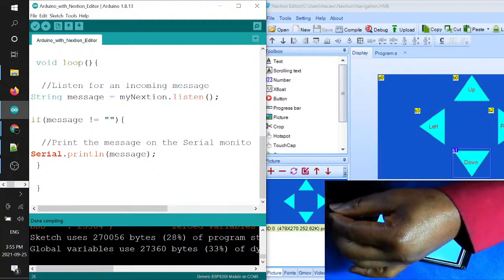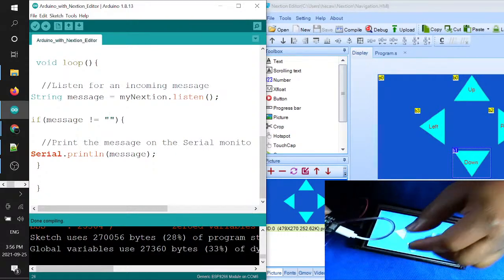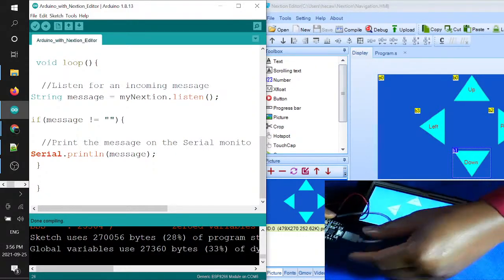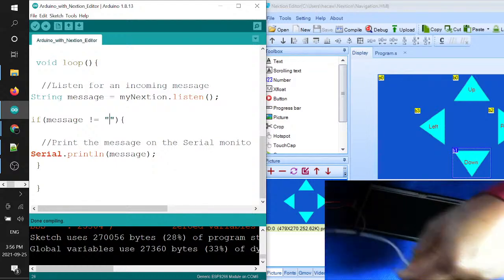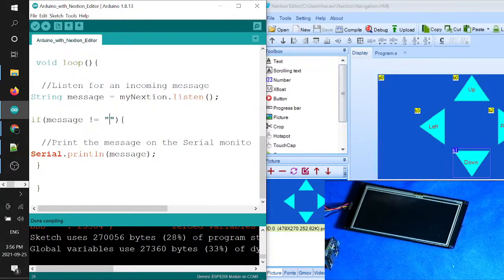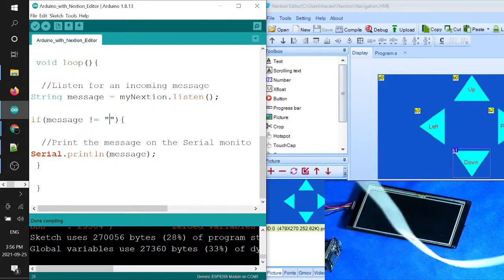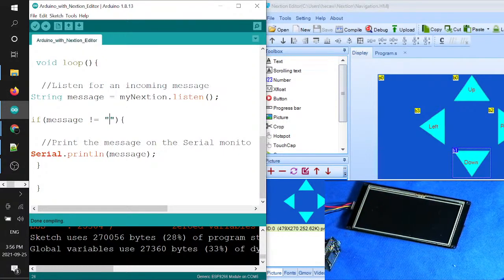Right, so when I try to install this, you can see the USB cable. I think this is a power only USB cable. It's not a data USB cable. So I'm gonna try to find a data USB cable because that's what you need to install the software on your Arduino. So let's see.